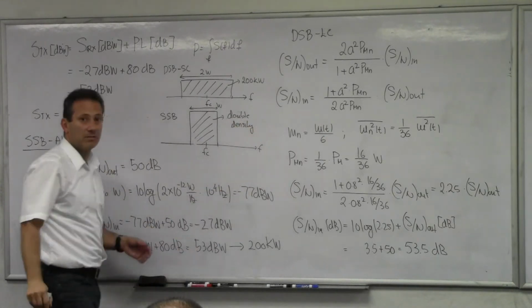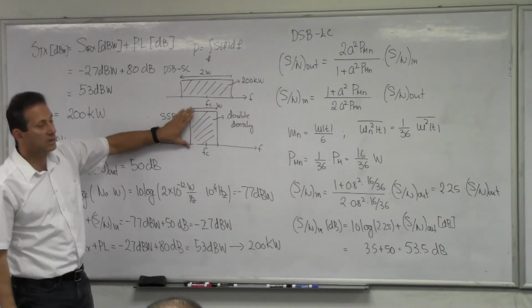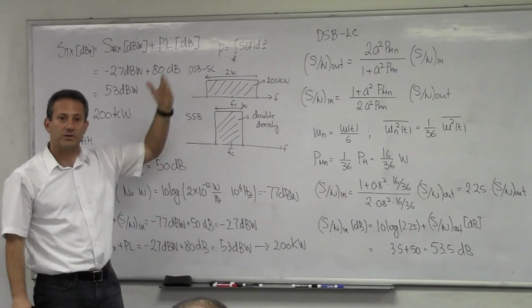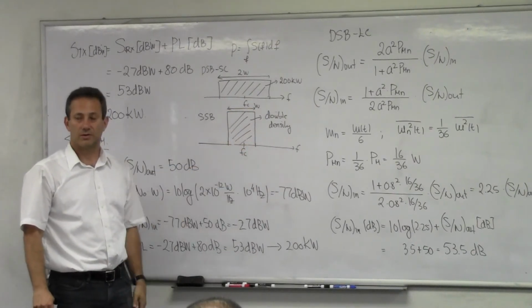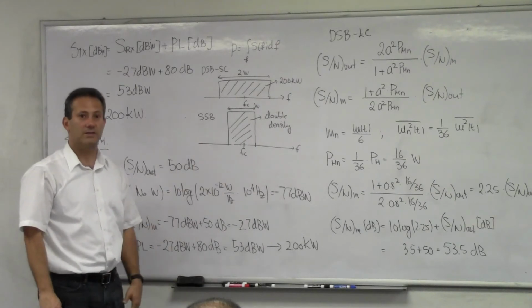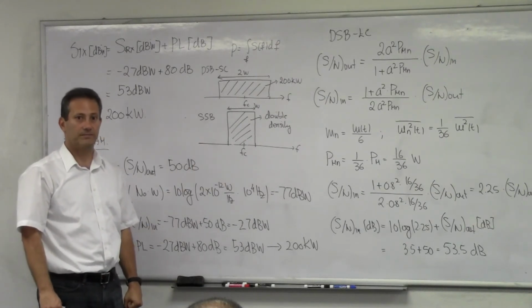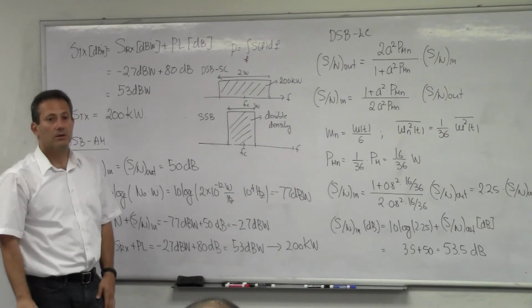So power is the same, indeed, right? But because you are shrinking the bandwidth, your power spectral density goes up. So that's the trade-off I was referring to. So it's the power spectral density that we're talking about. But the total power to transmit is equal.